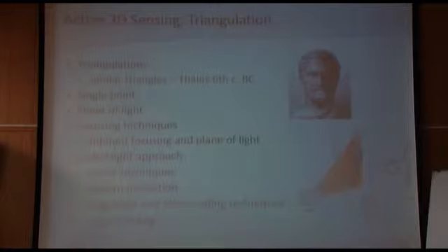So you can also use a combination of the whole thing. You can use coded light approaches with different patterns, with different gray codes and other coding techniques, color coding, whatsoever. The important thing is that you have some active pattern, be it different colors, be it different patterns, that is projected onto the surface. The camera is seeing this pattern, and with the distortion of the pattern you can recompute the distance of the points in the camera.